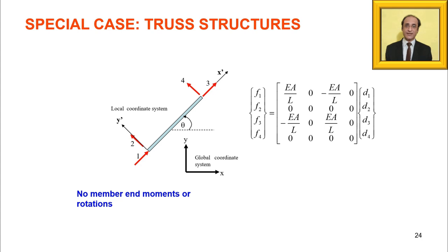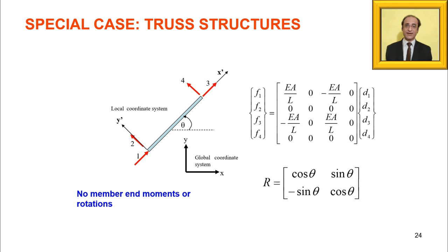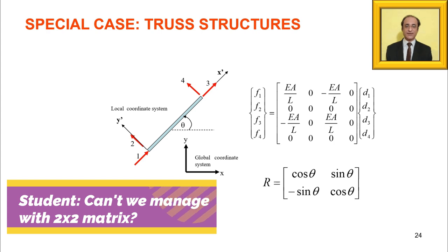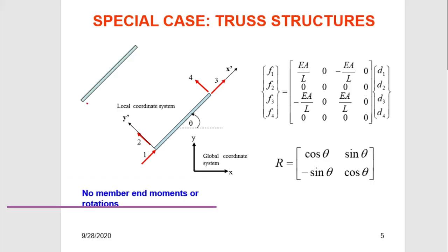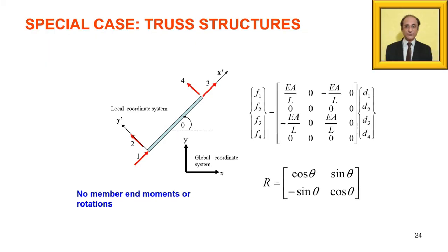And this is our joint rotation matrix. So here the matrix will be simply 4 by 4. Because finally we need forces in the global coordinate system. So this is our global coordinate system. What is the size of the matrix? 4 by 4. So local we cannot keep 2 by 2. That's why we have done 0 padding. Otherwise it will be inconsistent. So that's the reason. Okay.